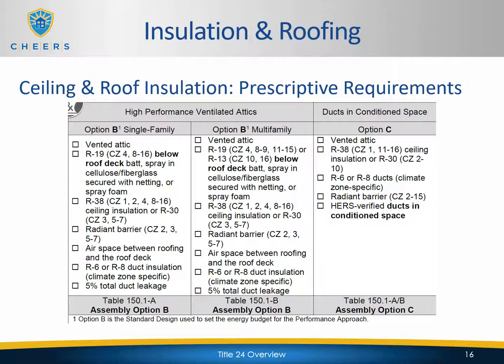So that's a prescriptive requirement that belongs with this option C. If you take that credit, then you are going to have the HERS rater go out and verify those ducts in conditioned space.